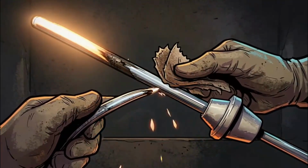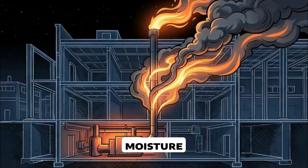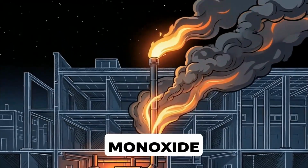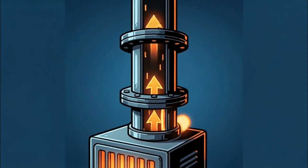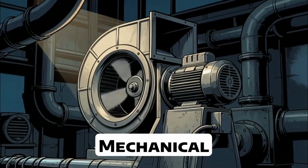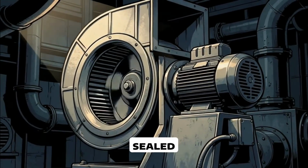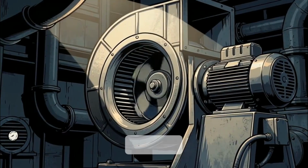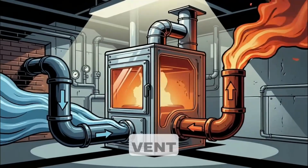Now, venting. The purpose of venting is to remove combustion gases, moisture, heat, and carbon monoxide safely to the outdoors. 3 major systems are tested often. Natural draft uses buoyancy of hot gases rising through a vent or chimney. Mechanical draft uses a fan or blower. Direct vent uses a sealed combustion system with outdoor air intake and outdoor exhaust. If asked which system uses outside combustion air, think direct vent.